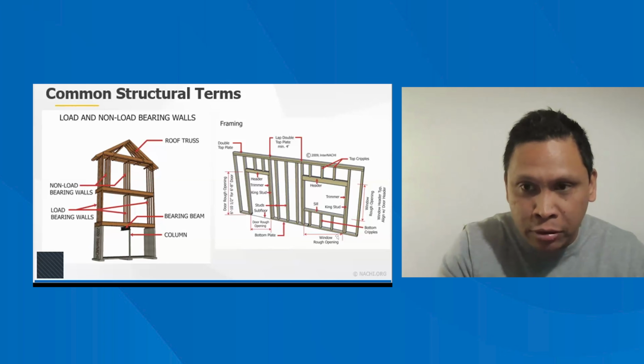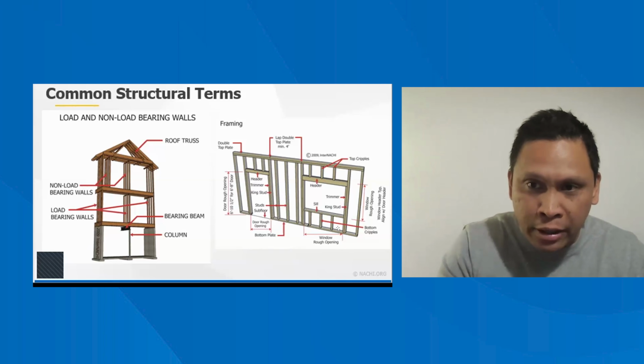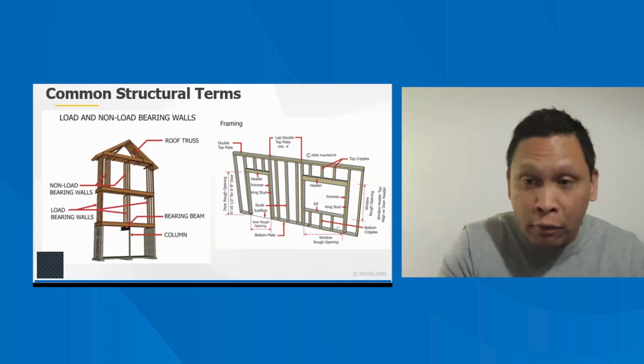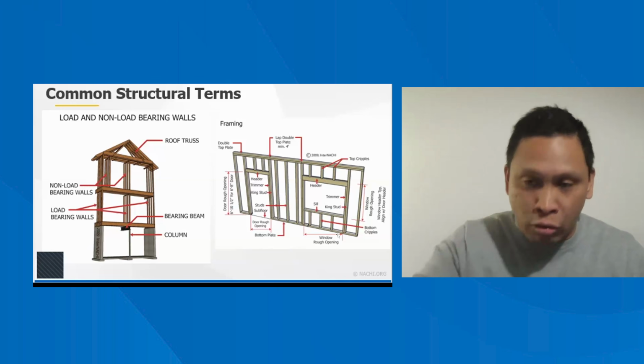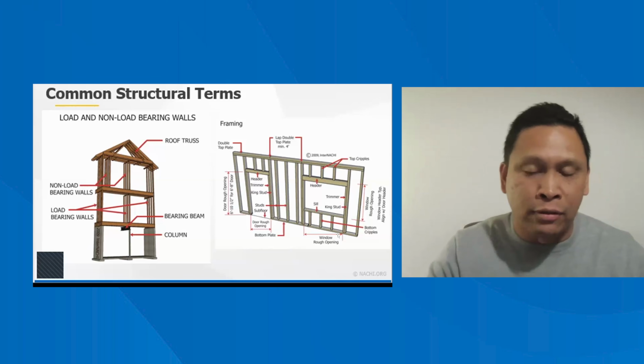And oftentimes, what you'll see the builder do, which is what we don't see on a resale or on a finished home for a final inspection because the drywall's in place, you'll see, or hopefully you'll see, squash blocks, so very short studs, almost like a cripple, to help support that king stud assembly system and create that continuous load path down into the next floor.